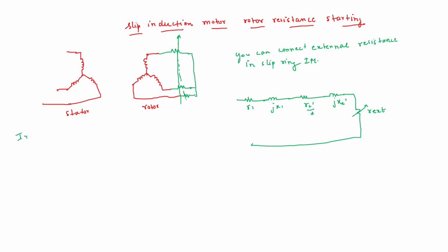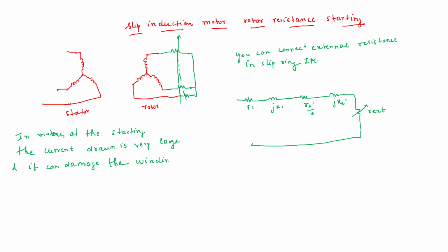In motors, at the starting, the current drawn is very large, and it can damage the windings of the motor. Also, it causes voltage dip issue.